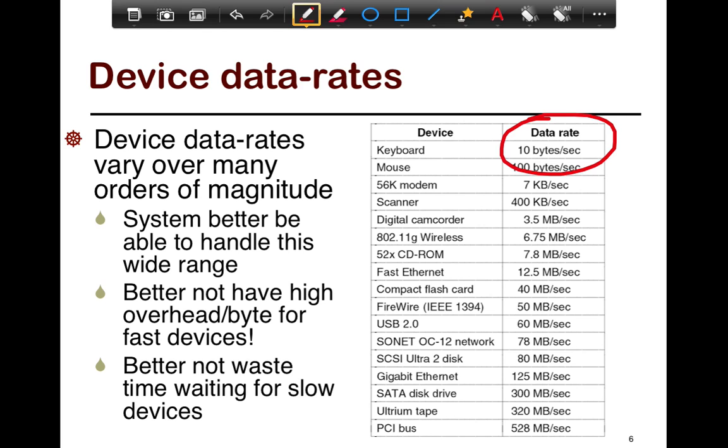If you had PCI activity at the same time, that's going to be slowed down because you're handling a much slower device. If you queue these different devices up, you could have a really slow device at the head of the queue blocking the rest of them. And so a big challenge as well is to make sure that you don't have such queuing delays in the system. You've got to make each I/O device independent of each other.